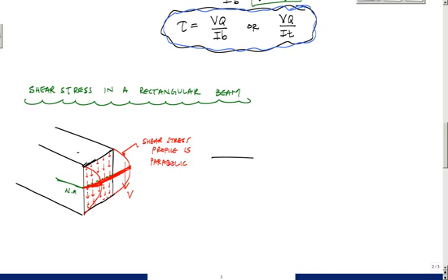And if I drew this in 2D, this is how I would draw it. Here's my surface right here. I have all my little shear stresses with the arrow being max at the neutral axis like this. And here is my neutral axis, NA right here. And the intensity of this is parabolic. Okay? And here is tau max at the neutral axis location.